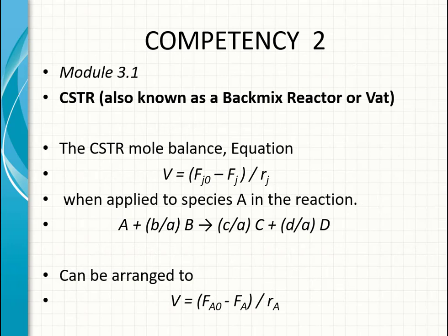CSTR, also known as back-mix reactor. The CSTR mole balance equation is that the volume is equal to Fj0 minus Fj divided by the rate -rj.